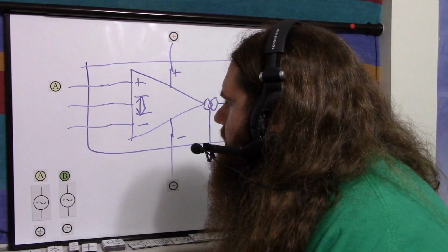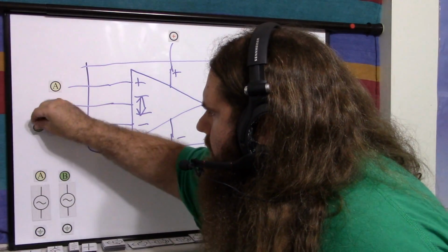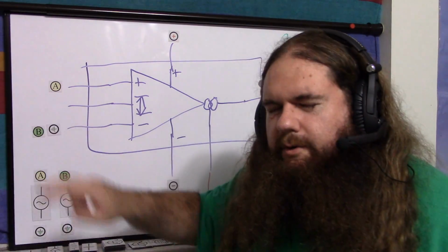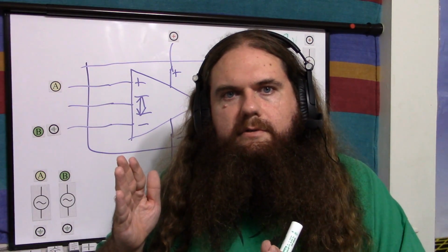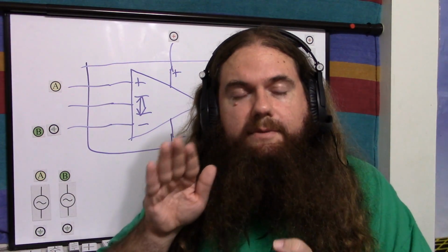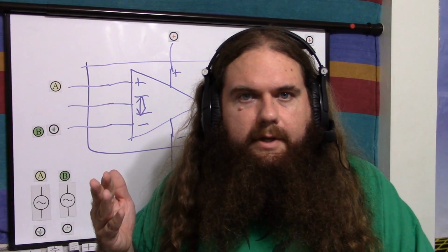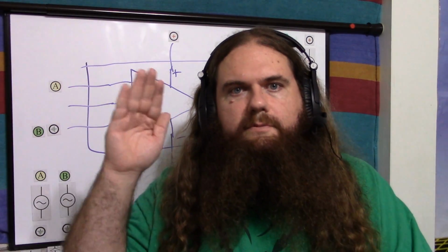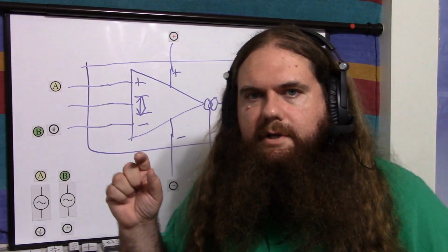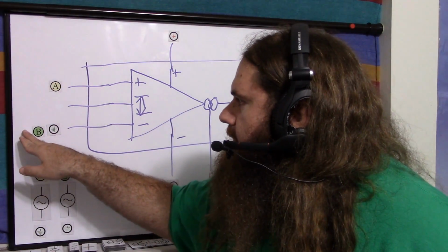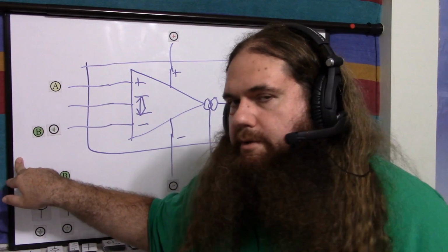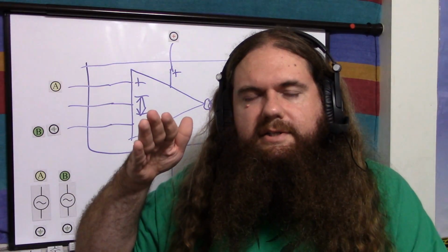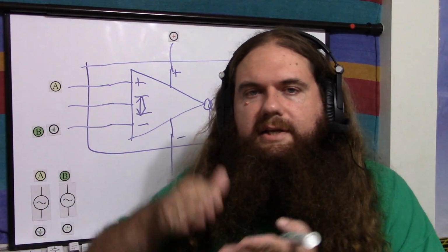So basically, if you have ground or B or whatever, in order to decide how to divide the voltage, you just have to say, what is the biggest input voltage I'll have? Difference. What's the biggest difference? So 1 volt peak to peak. So that would be plus 0.5 volts, minus 0.5 volts. So you have to say, okay, the actual difference is going to be positive or negative 0.5 volts. So I have to use a voltage divider so that the loudest the signal will get, so let's say 0.5 volts, let's say it can't go above that.